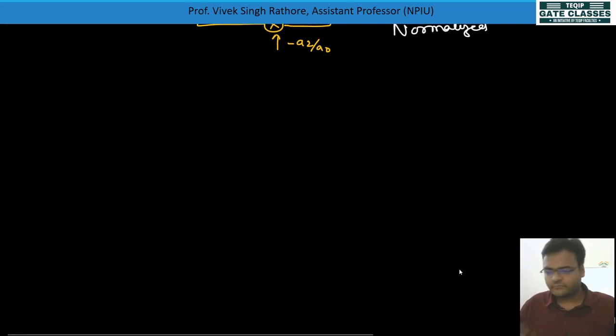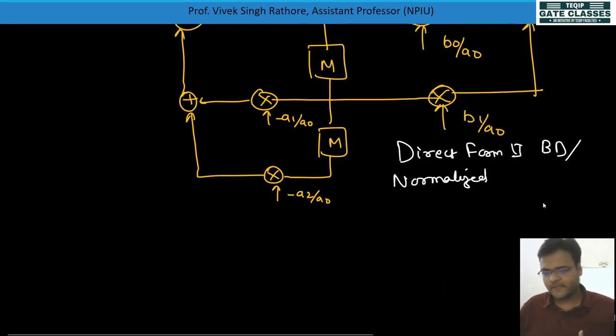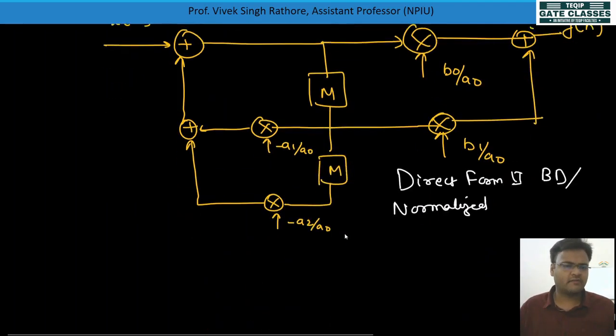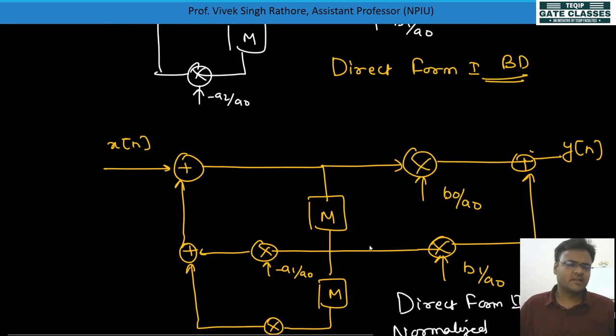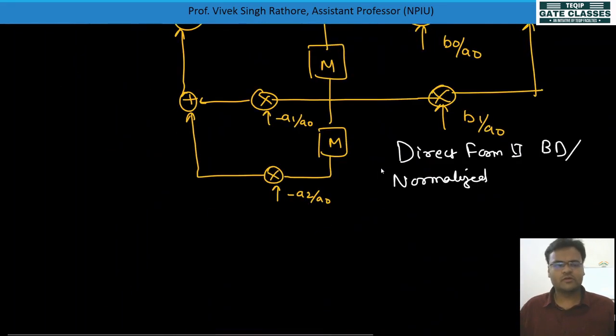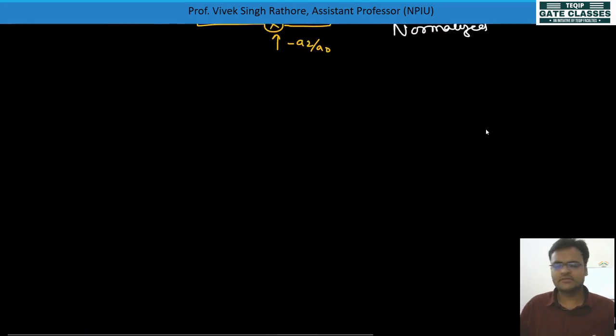Okay, so generally for research and industry, only the second one, direct form 2, is used because it has some common things and a lower requirement of delay factors than this. So direct form 2 is currently used, and research is also going on.